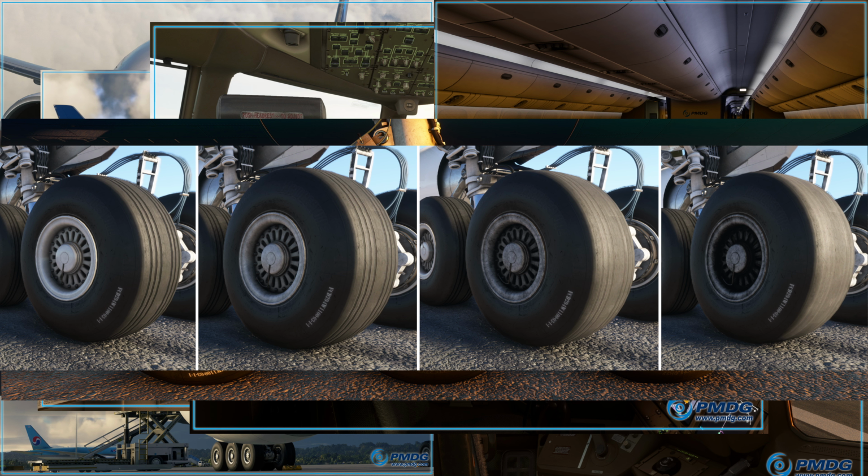But remember though, if you're in the high-speed regime of your takeoff, then a tire failure is not a reason to reject the takeoff unless the ability of the airplane to safely fly is in question. Always remember, it's better to take an airplane into the air and fly it back to have the full runway available for landing it again, other than rejecting a takeoff halfway down the runway or even further down. Those wide bodies can really eat up runway. You're going to see that in the video previews very soon.